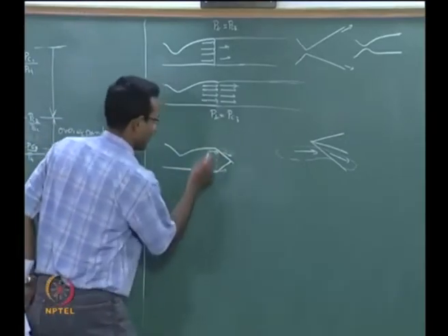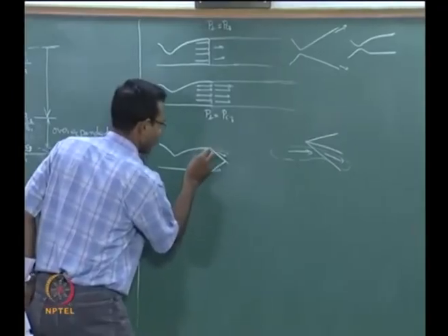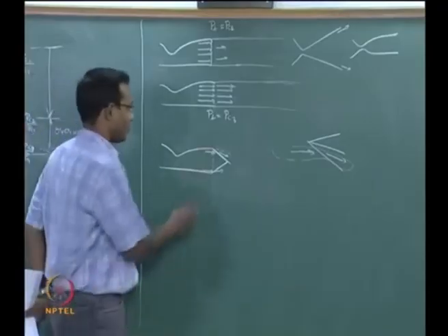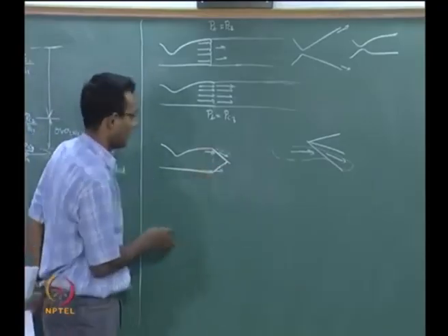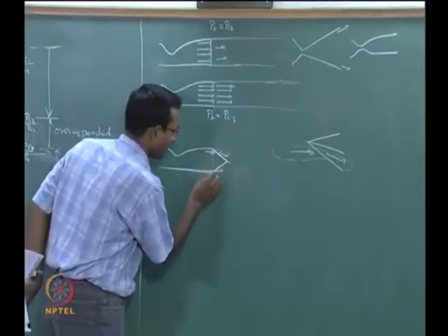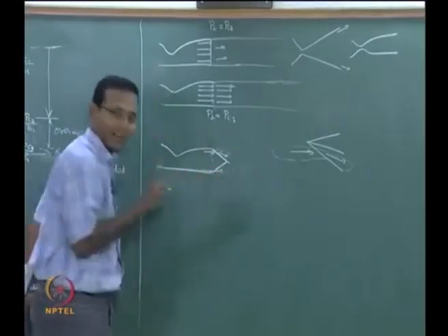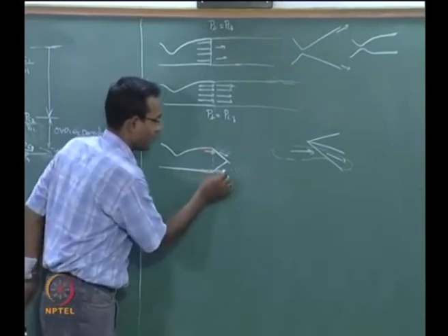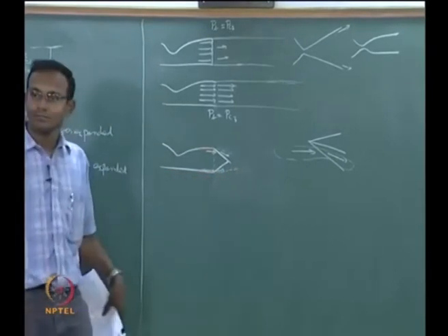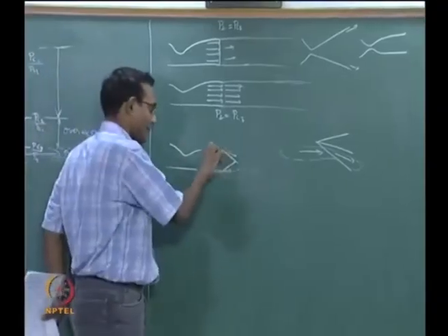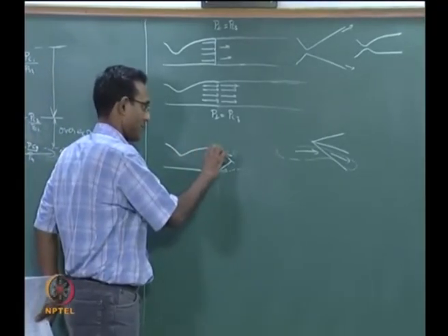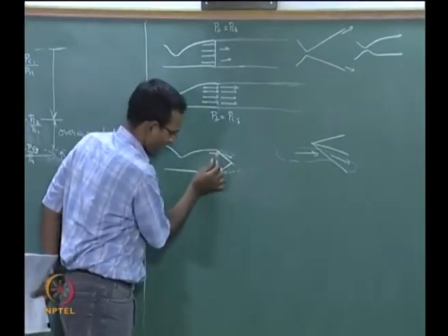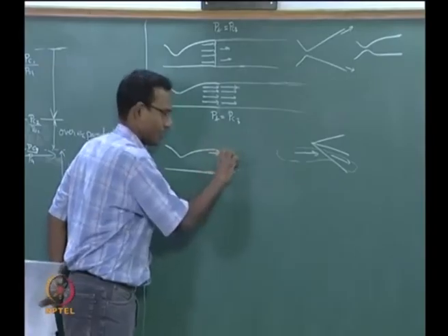Now that it is getting too confusing, I will draw this nozzle with red only near this portion. Okay. So this white thing is my shock, and so both the fluid elements are turned inward, which means now my final streamline, the jet boundary, is going to be turning inward, right. What does that mean? I think of that jet as one slab of fluid here. That slab of fluid as it goes in is getting shrunk.